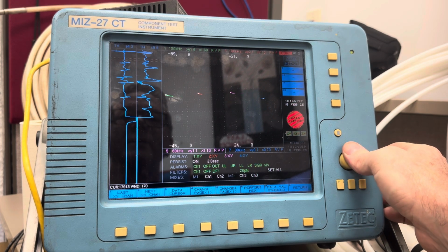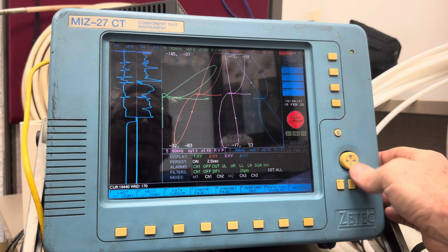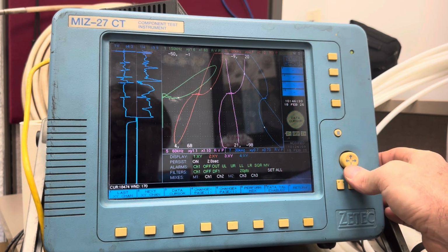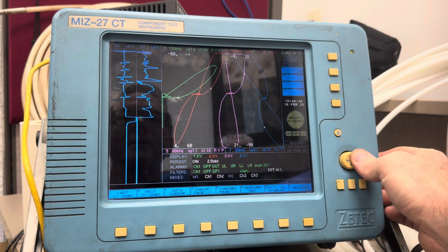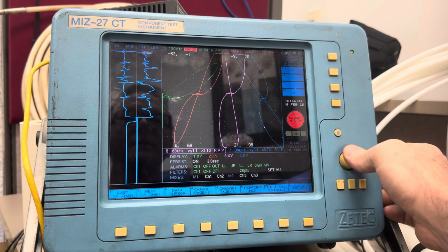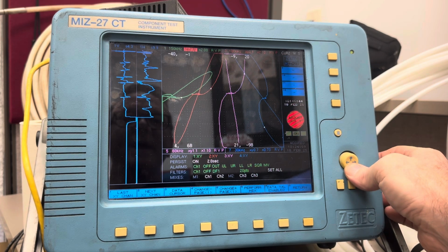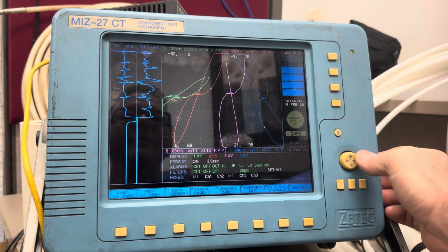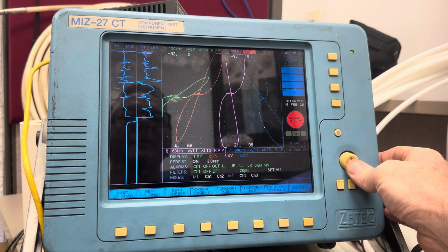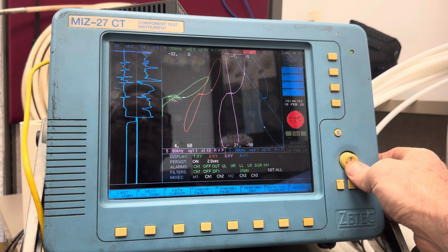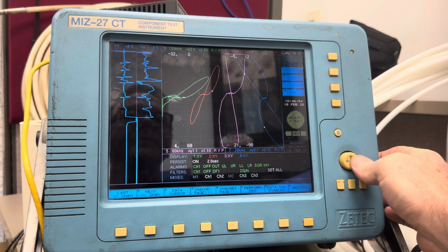And then we got a huge signal at the end, and that is a 360 OD 10% groove. Well, why is the signal so big? Well, from your studies, you know that the amplitude of a signal is a product of its length, width, and depth. In other words, the total amount of metal that's missing.